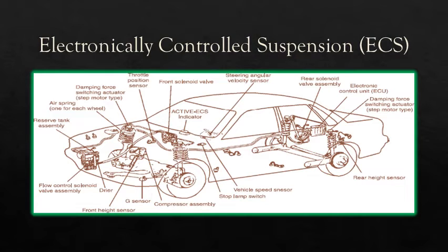Electronic controlled suspension. The Mitsubishi system with the acronym ECS has been designed to keep the car flat and level when riding over bumps, accelerating and cornering. It achieves this with damper valves that can be independently addressed by the car's suspension computer to vary their damping effect, additional air springs for load sharing, and also to alter the height of the car.